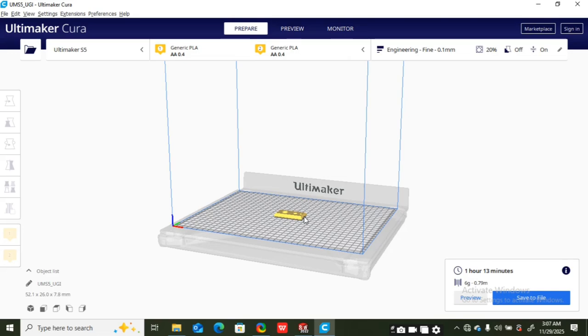If the 3D printer has a card reader, there should be a slot in your computer where you can slot in your card reader, and if you click save, automatically this software will recognize the presence of a card reader in your system and transfer the model into the card reader. Or if the 3D printer has a USB flash, then there should be a slot in your system where you put your USB flash, where it can be transferred. So that's actually what you need to know.